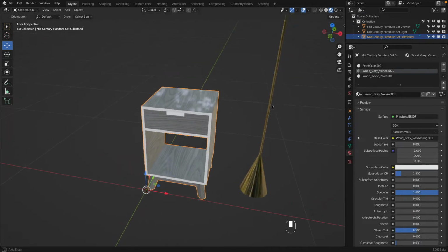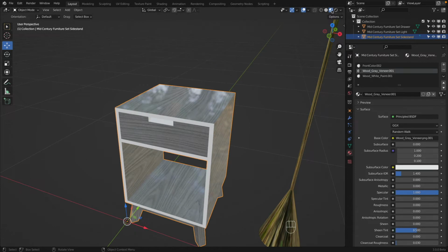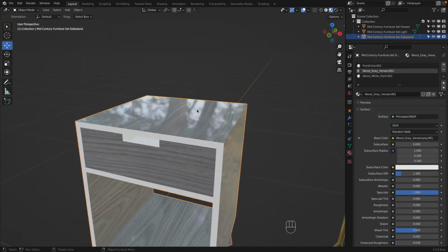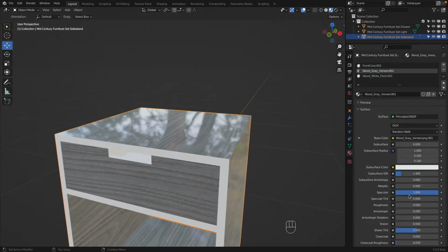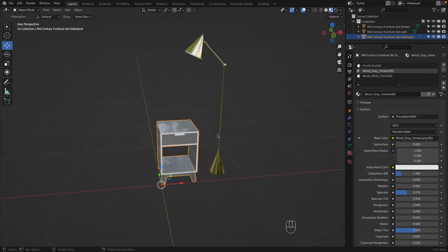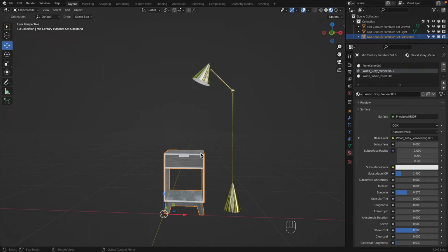If we set this high, when we have this material preview turned on, you can see there is a reflection going on. And when we turn the roughness on, you can see how the reflection then gets blurry. Okay. Very good. Everything we do here right now is not meant to give you a PhD in it.